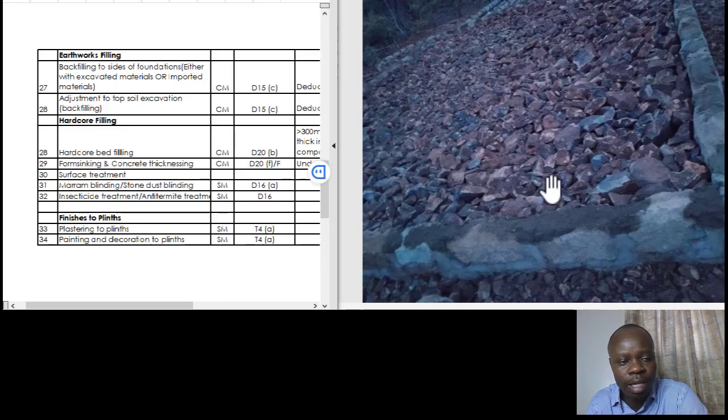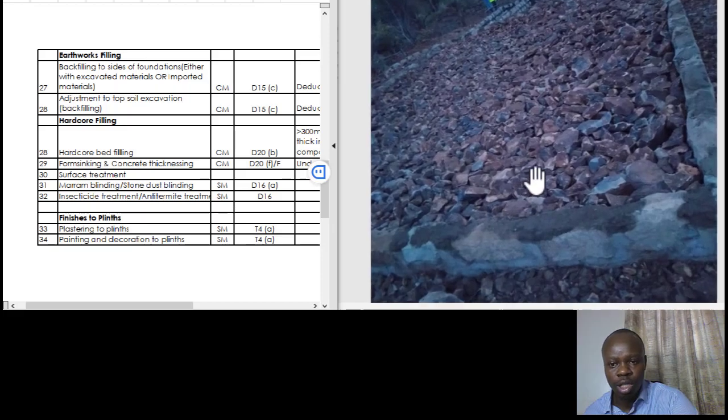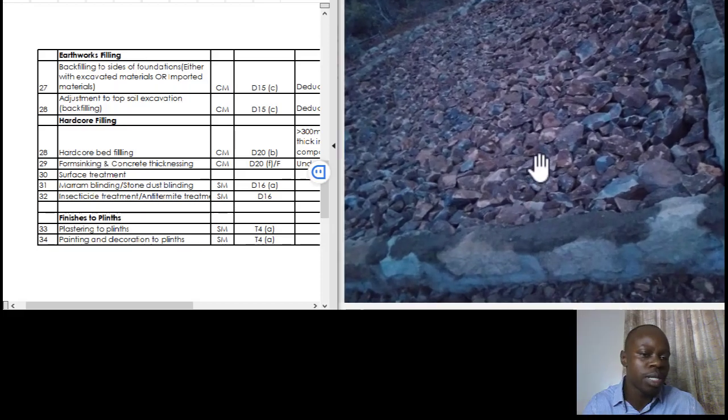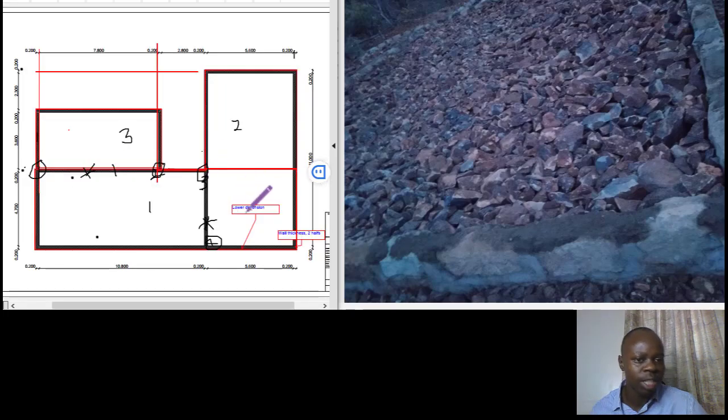But being that it's within the walls, then there are two ways that you'd approach it. First of all, you'd measure it within the spaces of the wall. For instance, in this plan, you'd measure it, number one, for maybe part 1, you just measure the area that is within that particular point, okay, within those walls. So basically you exclude the areas for the walls. Alternative 2, that's now based on your assessment, you can just do the exact area where you had your slab.